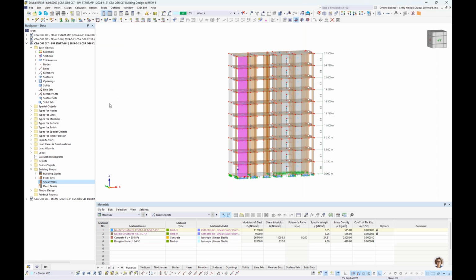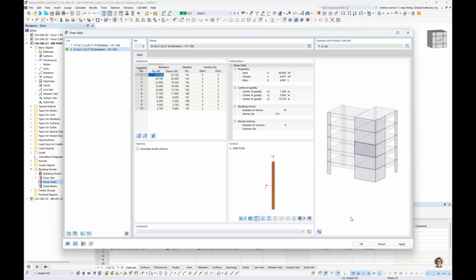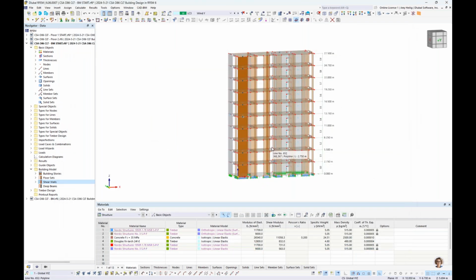as a shear wall. What the building model will do is to simply take these 2D surfaces and sum up the internal forces and present it to us as though it was a simple member, almost like a column spanning up through these shear walls. This is going to be much more user-friendly when we're designing our shear wall, so that we can immediately see what are the total shear forces in this 2D surface, what are the total in-plane bending moments, and we'll see this in just a minute with our calculation.